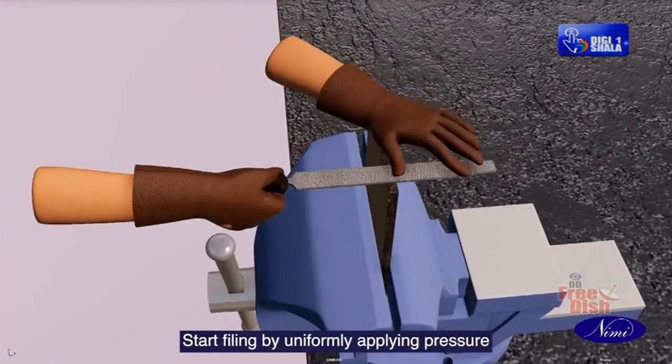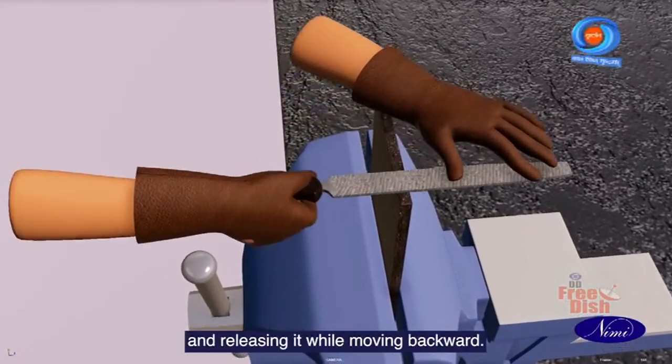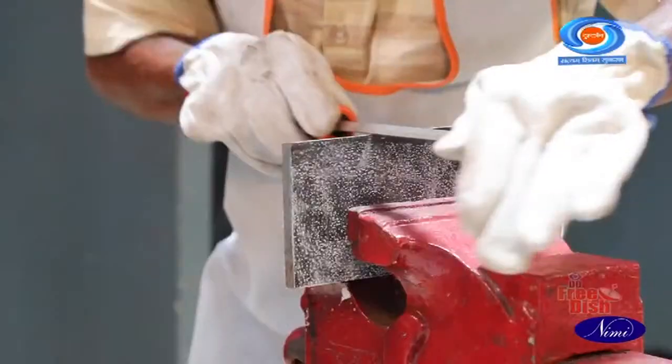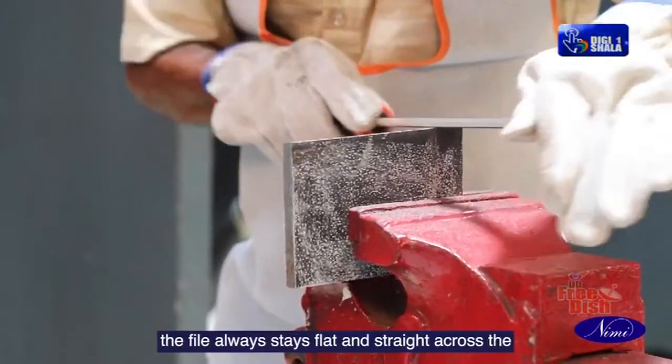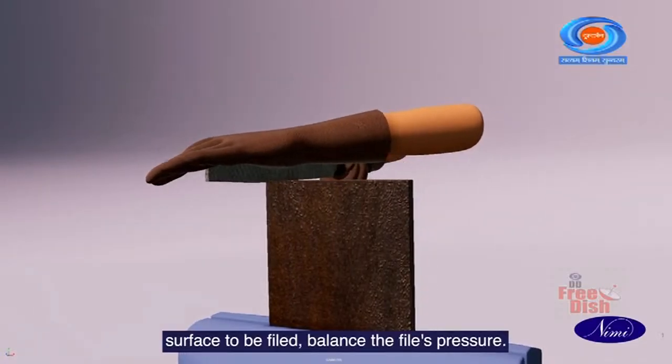Start filing by uniformly applying pressure to the file while moving forward and releasing it while moving backward. Give a few more strokes to make sure that the file always stays flat and straight across the surface to be filed. Balance the file's pressure.